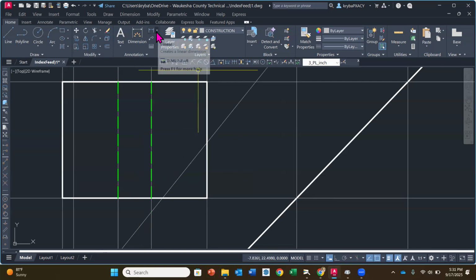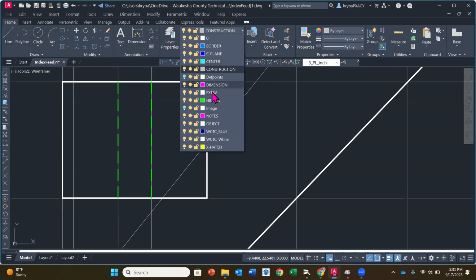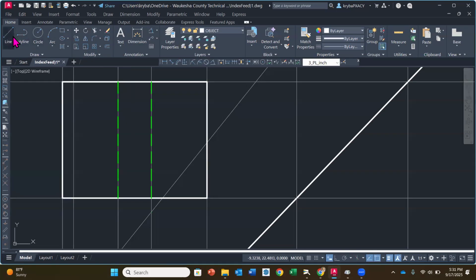My end result is 50. So if I go to an angle dimension here and I click on the horizontal to that value, I did still, oh, I know why. I got to put my regular line in. It doesn't want a dimension to a construction line. I don't know why. It's kind of silly. So I have to put my line in first, and then I'm going to dimension it. So if I go from here to here, now it's going to recognize it's that 50 degrees.